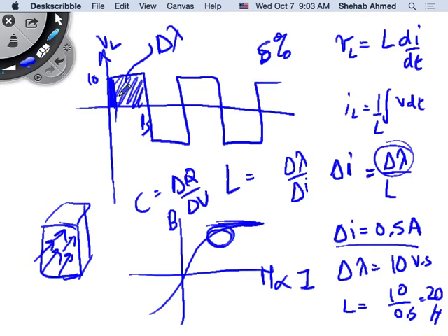He can use an air cored inductor, or maybe sandwich, since printed circuit boards are multiple layers, a core material within two layers of a circuit board and make an inductor that way. He can live with stuff like that because he's pushing the frequency limits.